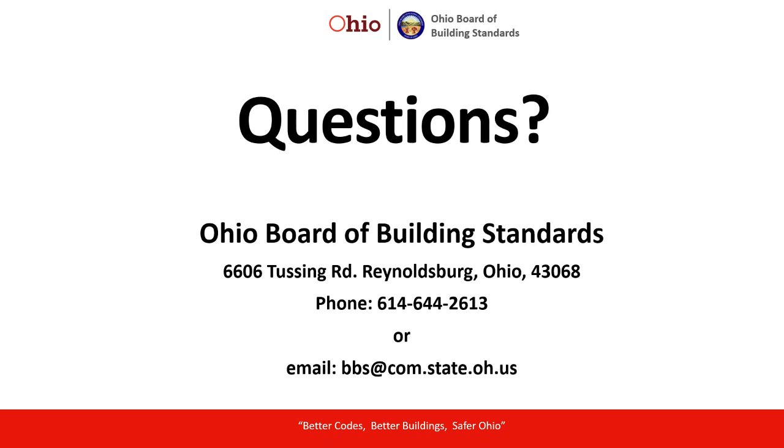Great. Is there a minimum width of interior doors in a residential house? There is not a minimum width for any door in a residential building other than the exit. A residential building, in other words, a building regulated under the Residential Code of Ohio, is required to have one exit, and it has a minimum dimension. All the rest of the doors do not have a minimum dimension.